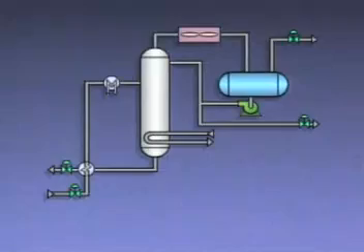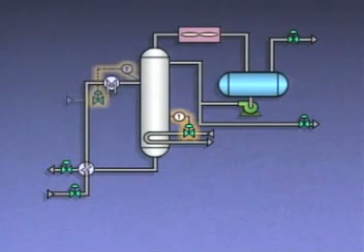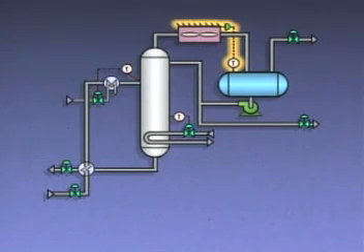Each control loop consists of instruments and devices that work together to monitor and control the value of a process variable. In our example, the primary energy flows are controlled by a reboiler temperature control loop, a feed preheater temperature control loop, and a condenser temperature control loop.